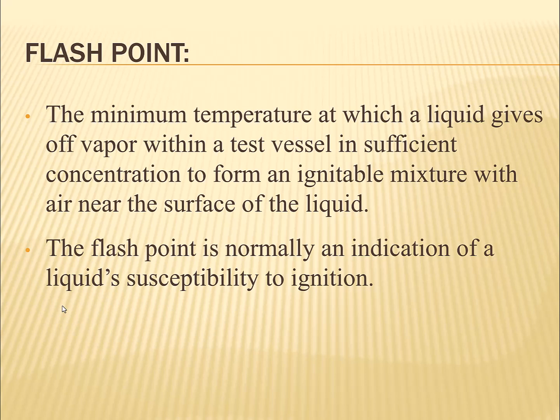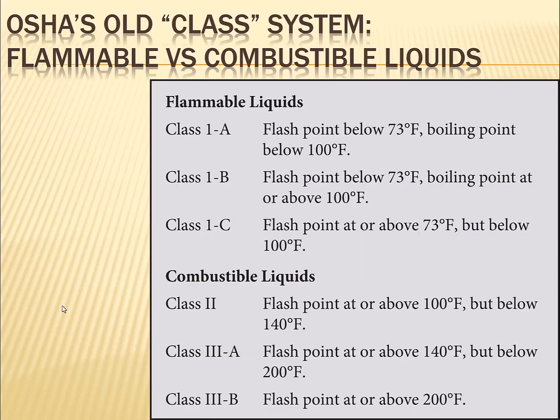What you're trying to ignite is the gas that's evaporating on the surface, the vapor. And so we were actually more successful when we weren't even trying to get it into the bucket and just shot barely over top of the bucket through the cloud. But it just goes to show you've got to have the right concentration. Now, Murphy's Law says if you thought you could get away with not worrying about such a thing, then that concentration would just magically get to be just right, and then you'd have an explosion or a fire.